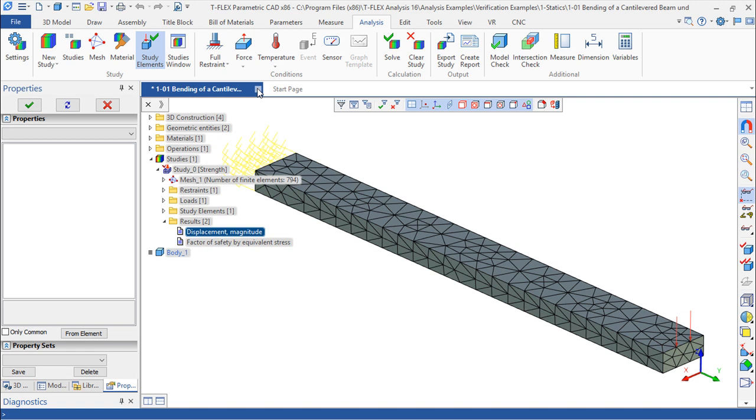Then we have the stress analysis, where we can open the equivalent stress, and we can see the stresses that are present in the system. So it's another kind of analysis. So we can analyze in what locations and in which elements we have the largest stresses, where they develop. And we can compare also the maximum calculated stress with the allowable stress for the model material, so that we can see what is going on.